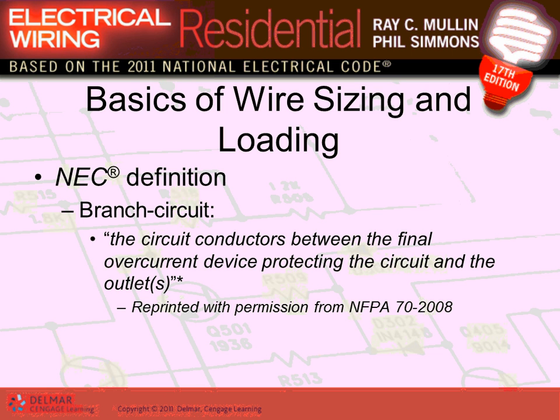One circuit is the one that brings the power to the building. That's called the service entrance conductor circuit. We brought the power to the building. Done with it. The second circuit, down in the basement, is the conductors that bring the power from the basement to this panel. These are called feeders. Cool.